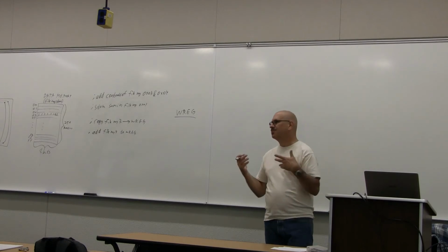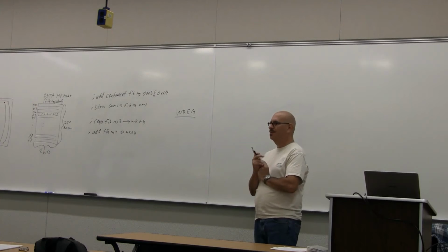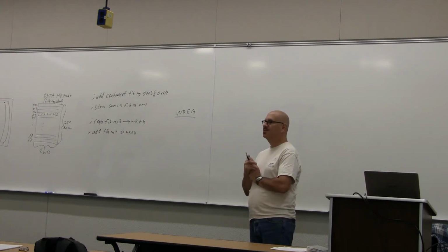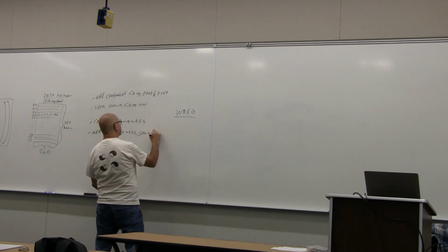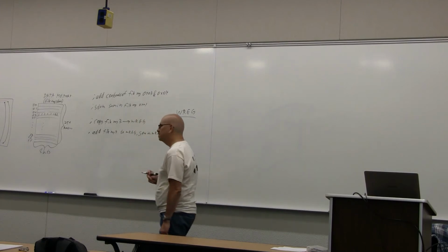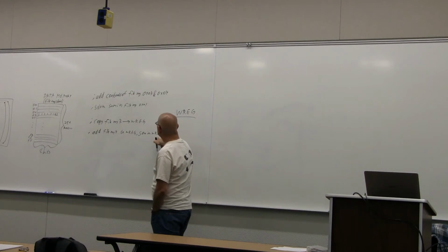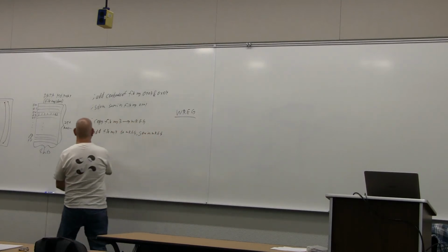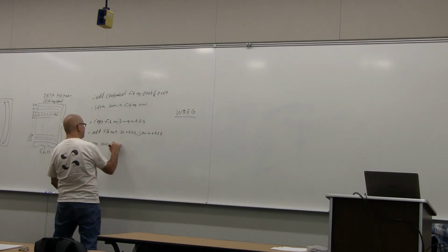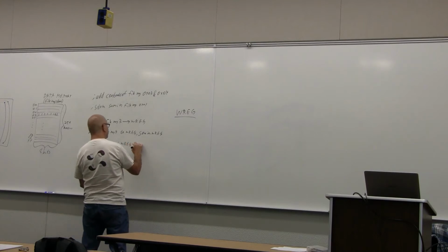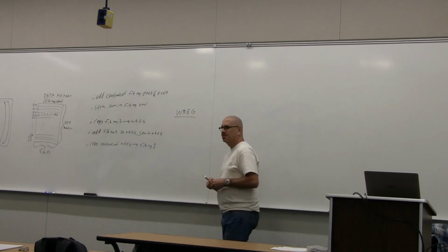And we can save that in one of two places. We can either save it back in file register 4, or we can save it in the working register. If you don't want to destroy the contents of register 4, let's save this in the working register. So now this is the sum of file registers 3 and 4, and we wanted to store that in file register 1, so now we can say copy contents of the working register into file register 1. So it takes 3 steps.